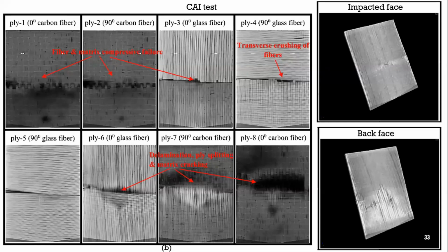You covered it. Yeah. So generally, porosity or these air pockets inside the composite laminates is a very common problem that everybody faces. For that, you can employ methods such as vacuum bagging, or you can go for some sort of vacuum generation where you just remove all the air pockets and air bubbles in the uncured matrix itself.